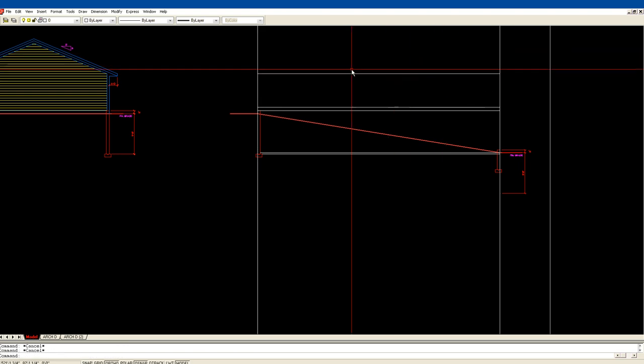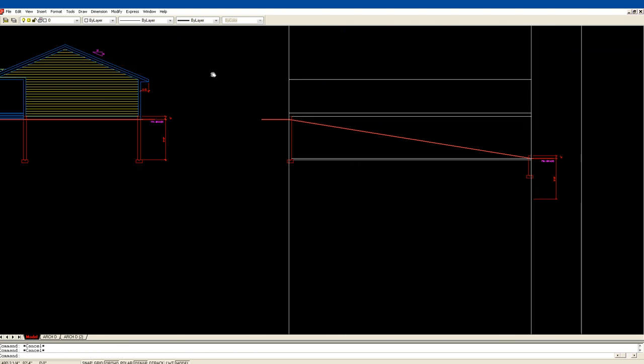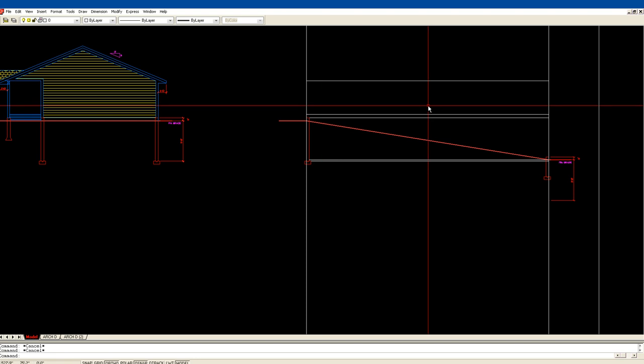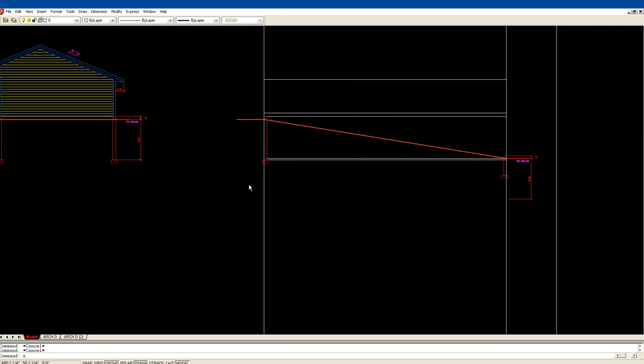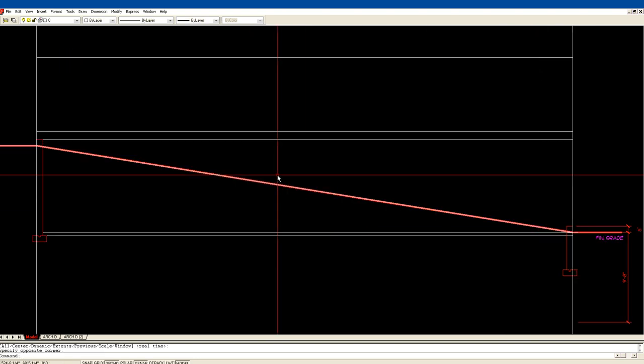Okay, so we have the same setup that we had when we did the front elevation, but this one varies a little bit. There's a code that says we are not allowed to step a concrete wall more than 2 feet, more than 24 inches in height, and not less than 24 inches in length. So that's confusing, but let me show you how.